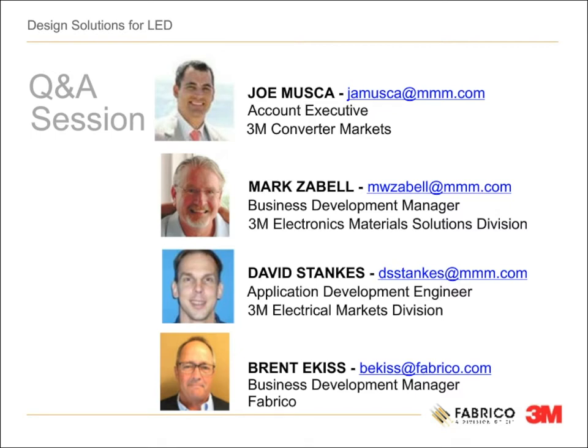Our next question is, I've always used thermal grease as my interface material because of its good thermal performance. What kind of thermal performance can I expect from an acrylic or silicone pad? I'll take that one also, Steve. Most of the greases out there are in the 4 watt per meter Kelvin range in conductivity. And we can offer 4 watts, even higher, as much as 5 watts with a silicone pad, and as high as 3 watts with an acrylic pad. So very comparable.